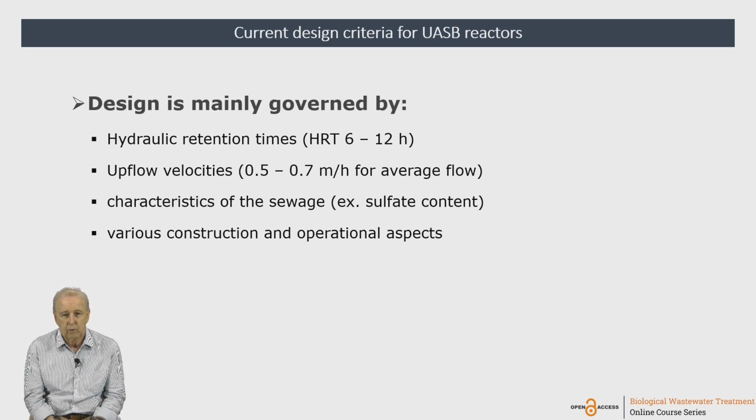So before we go to every design criteria in specific, we call attention that first, the design is mainly governed by the hydraulic retention times, in other words, by the hydraulic loading rates and not by the volumetric organic loading rates. For instance, kilograms COD per cubic meter of reactor per day. So this is not important because we are talking about a wastewater that has a low concentration of organic matter. So what really matters for us here is the hydraulic loading rate.